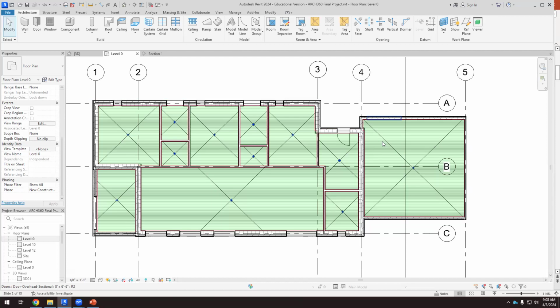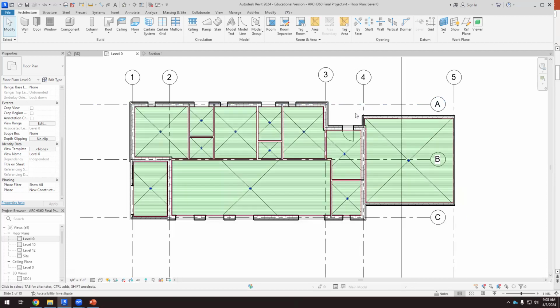But your energy consumption will be way higher if you heat up your garage. On the other hand, if this is an unconditioned space, when Revit does the analysis, this is not an outdoor space, so the temperature of this space is not the outdoor temperature, but we don't have a heating system in that space. Okay, so this is the first thing that we have to understand: the difference between conditioned space and unconditioned space.